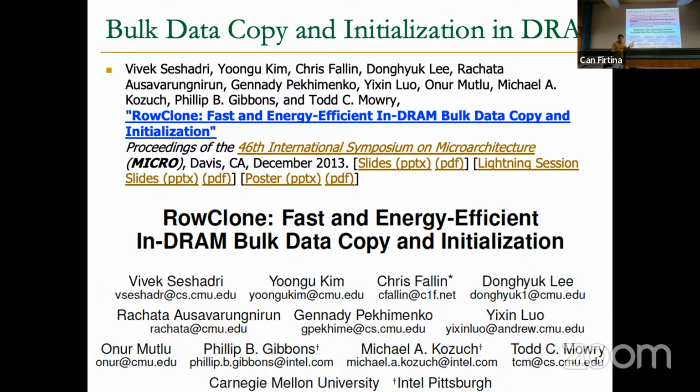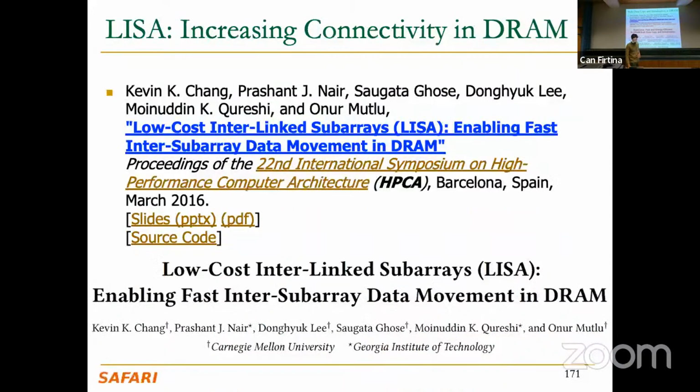There are people in another university, in another group, who have even shown how to do this operation in real chips that you can buy in the market. So it's not that far. In your current CPU, your current cell phone, etc., if you want to perform this operation, you will have to bring the whole row, let's say 8 kilobytes or 4 kilobytes of data, to the CPU all the way through the cache hierarchy, and then write them back to another row, maybe even in the same DRAM subarray. So imagine the large amount of performance improvement and energy savings that this can provide.